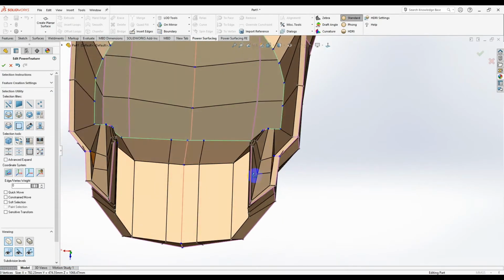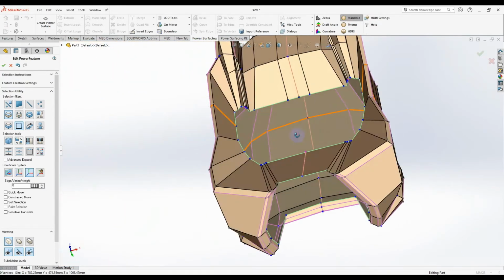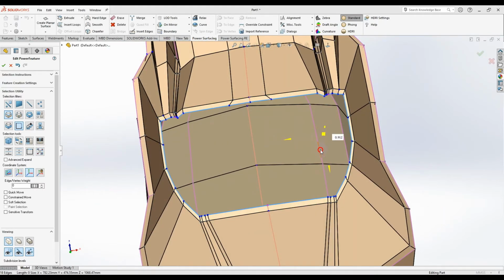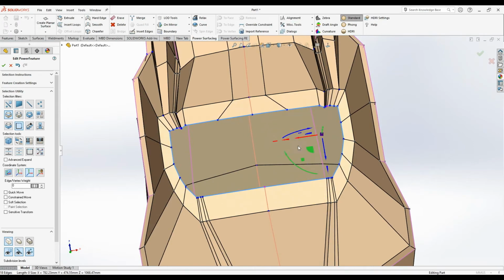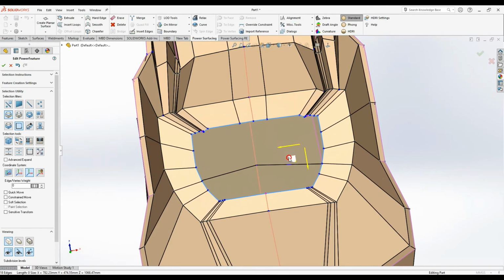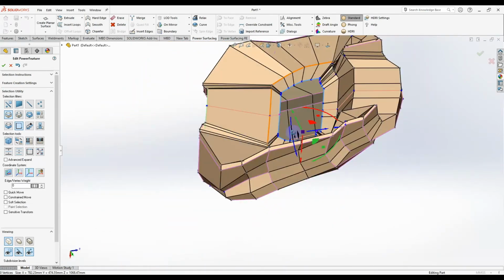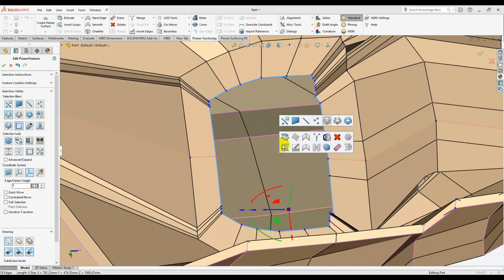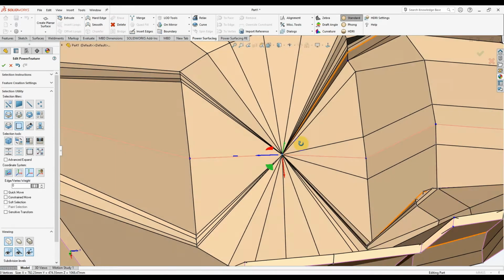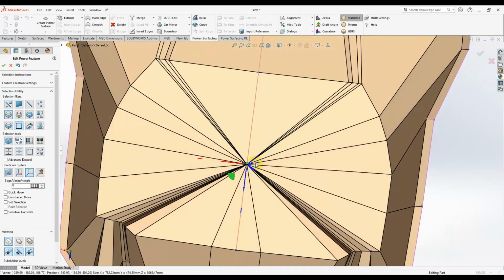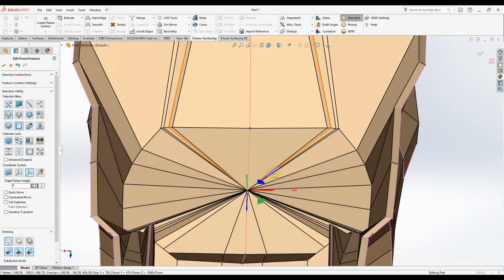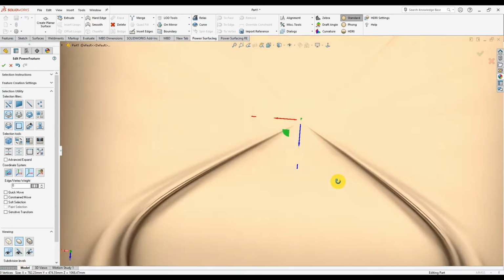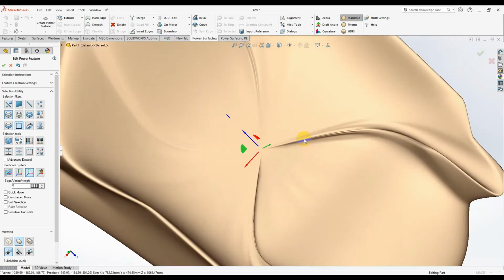Okay, hold the A key and snap again like this. If you just right click and use merge, it's gonna merge the whole points together, and this is fully wrong. You're gonna have the same result, so it's just closed, but not closed right.